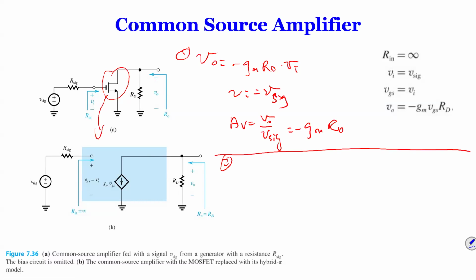input and output resistance? Well, in this case, we actually already did. So you guys know that our input resistance is infinity, because really you look at the input, it's open circuit, so it's infinity. And your output resistance in this case, ideally you should add ro here, where RO equal to VA over ID. So if that's the case, your output resistance will be simply RO in parallel with RD.